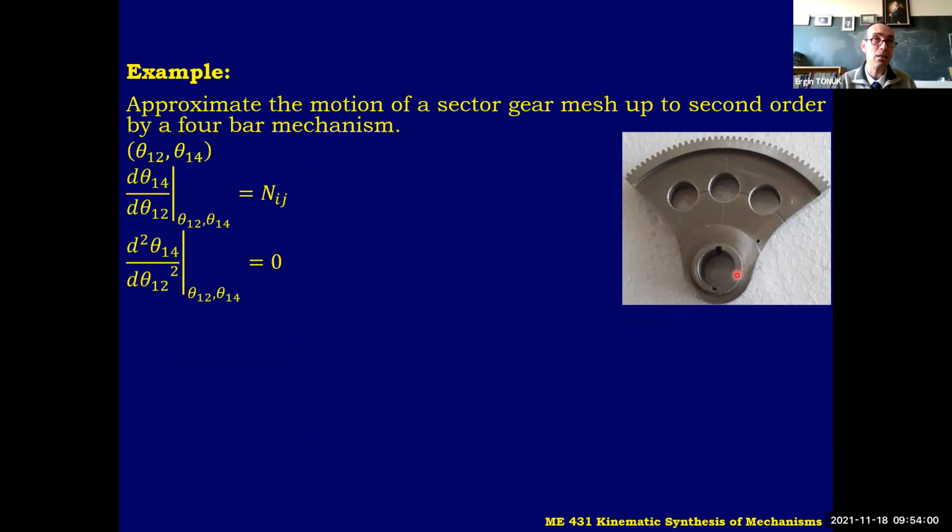Gears, they are linear. That is, the speed ratio is constant, as you might remember from 301, which is the gear ratio for simple and compound gears. Say you may want to duplicate the rotation of this, so use this big sector gear and a smaller one meshing to this, so that when you rotate this, for example, by 60 degrees, the other shaft is going to rotate 120 degrees, but not full rotation.